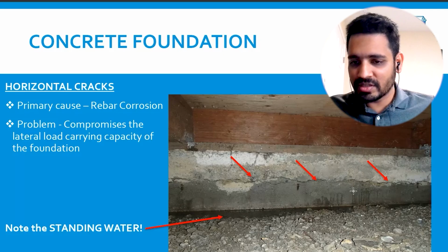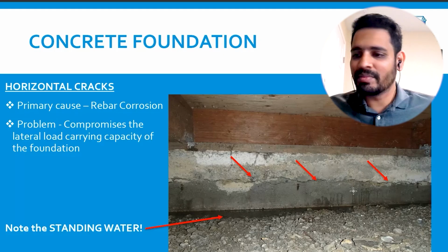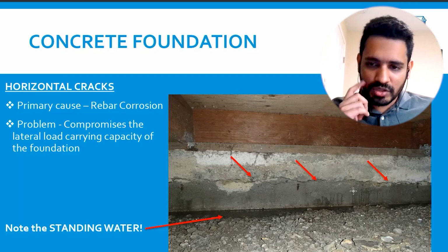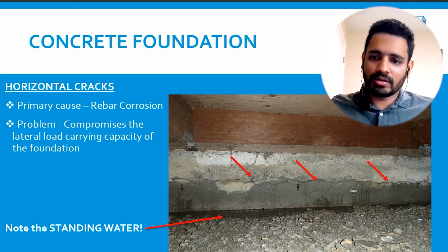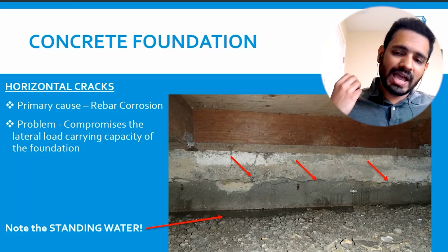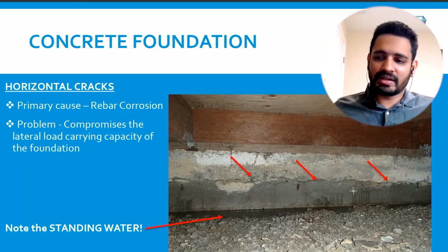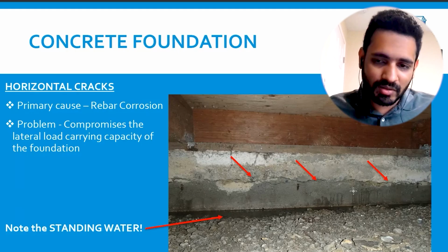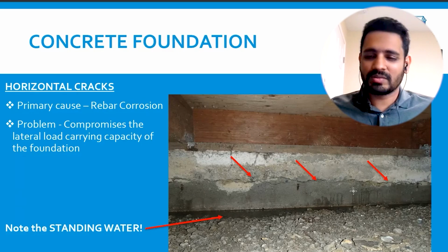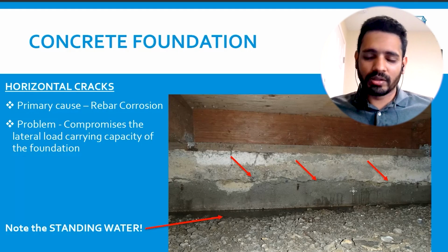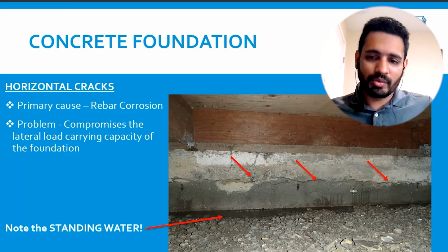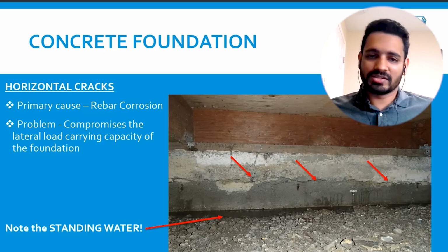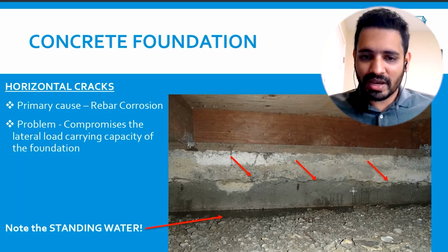Even if it is a softener that was installed a few months ago, I make it a habit to check behind the softener because the system that they use to soften down the water, the chlorinated system, you can still have a little bit of diffusivity from that entire system. It's a sealed system. Yes, I totally understand that. But I've seen horizontal cracks behind water softeners, mostly old water softeners, all the time in my inspection. And I make it a point to move them just to make sure that there's no cracking that's hiding behind the softener.